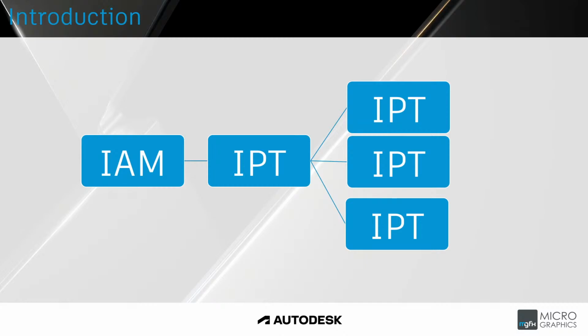Now, when we think about layout designing, first you work in the assembly environment. You'll create your IPT, that would be your 2D sketch layout, and from there you'll start creating all your components or parts as needed or required for your layout assembly.